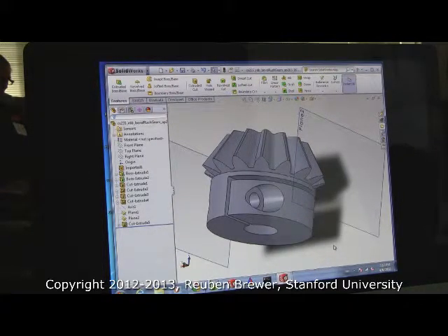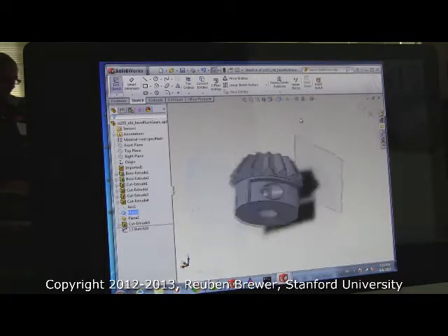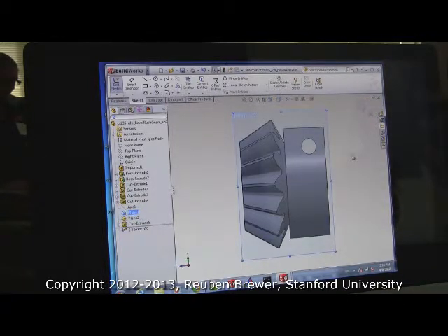Okay. So now select the other plane. Does everyone have that hole? Okay. Select the other plane. We're going to do a similar hole on the opposite side. Select that plane, extrude cut, do the normal button so that we're looking at it like this. When I press the plane, it shows the dimension. That's fine.